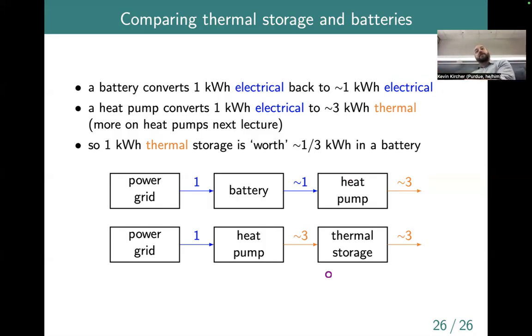But then you can also discharge heat from that stored hot water. Run a pipe through an air duct and have a fan to blow air over it, something like that. Then you can get away with a smaller heat pump because you have a secondary heating source in the basement. So you can save on the upfront cost of the system. But it's a complicated question, and this is why PhDs can write papers about it.